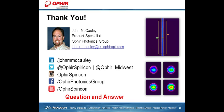Let's see, looking down here: what will the beam measurements do when something is wrong with the laser? I guess probably the best way to answer this question is, number one, take a dynamic laser measurement periodically to see how your laser is trending. By trending I mean from the time you turn it on to several minutes after the laser is turned off.